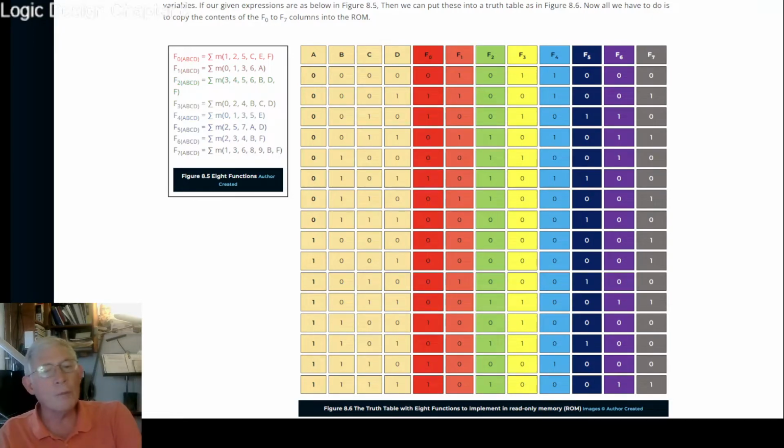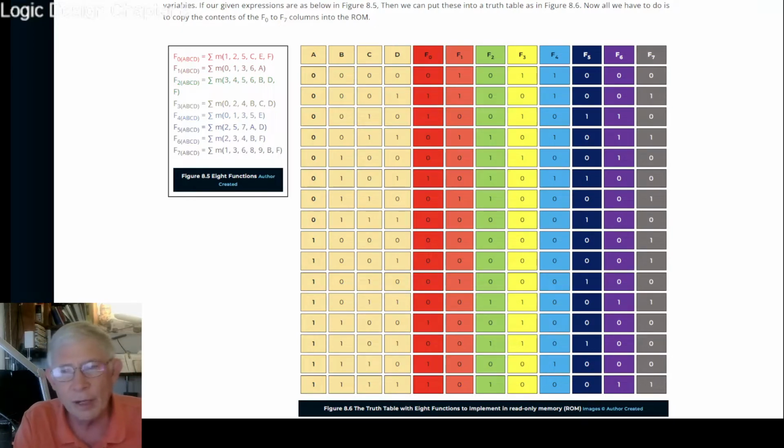Now, these ROMs are electrically writable and electrically erasable, and you have some extra inputs to the chip to change the outputs into inputs and to actually do the writing. Sometimes it requires a slightly higher voltage to make that happen, and there's usually a programming power pin that you have to zap with a little higher voltage. In the old days, it used to be 21 volts for like 5 milliseconds or something, but it's nothing like that now. Now it's maybe 6 volts or 5.5 volts or something. The requirements to program these things are pretty straightforward.